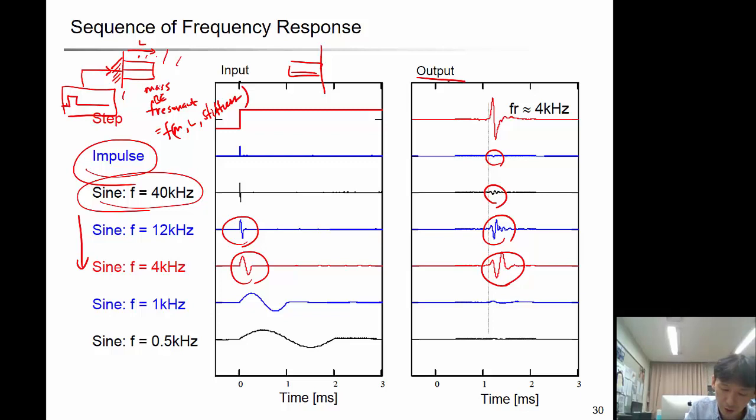So actually this bender is embedded in the soil. The resonant frequency will be a combination, integrated together by the bender characteristic and the soil characteristic. So initially when people found the bender element and suggested methods using it, they recommended a single cycle of the sinusoidal wave for the excitation.